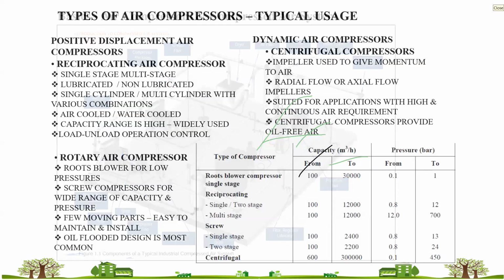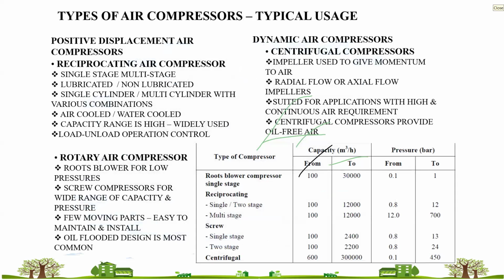Then these pressure ratios can be different for different compressors. You can't use a single-stage screw beyond 13 bar because the economics and ergonomics can be on the higher side. So different pressure ratios are there according to capacity and pressure. This cannot be used in your MCQs, but which has a higher energy consumption, air cooled or water cooled, or which has better efficiency, that can be used in your single mark questions.